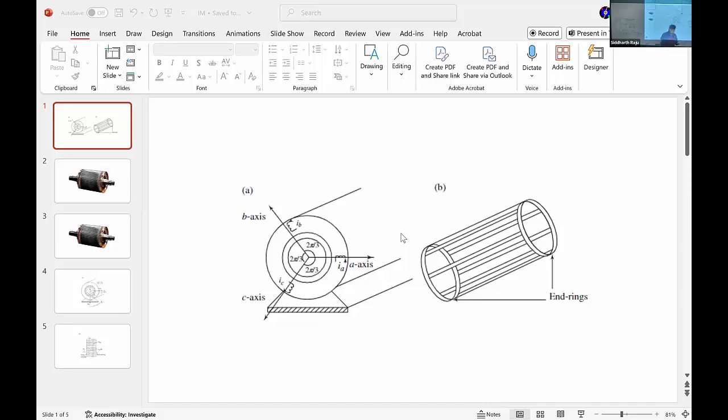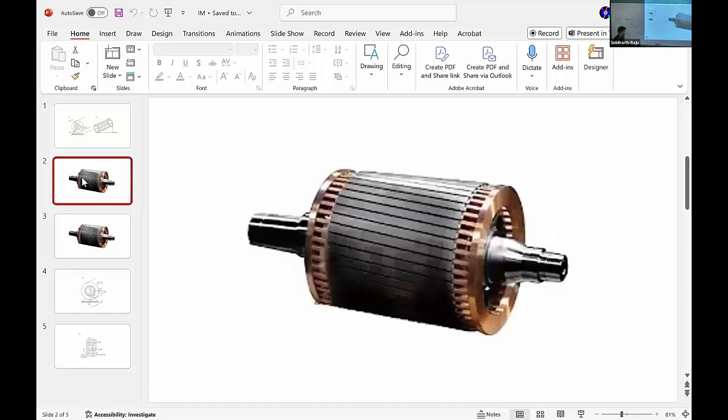So what this is basically, right? We take a whole bunch of copper rods and we solder the ends of the copper rod on the top and the copper rod on the bottom, right? And we will put this all inside stacked iron plates. And then we have these set of copper rods which are going to be carrying the current and creating the magnetic field. And on both ends, they are completely shorted out.